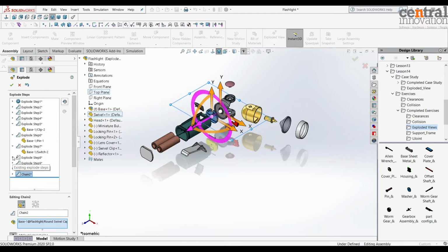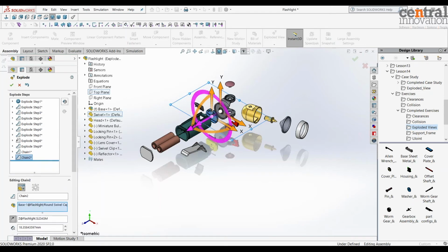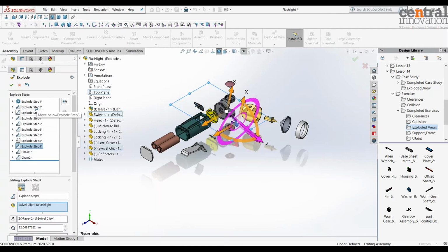Let's go back to the place that it keeps a recording of your steps. If you remember, I told you that the order of your steps matters for exploded view. So if you do your exploded view and have a look and see that you are unhappy with the order, you can simply, like Feature Manager 3, reorder your steps from here.